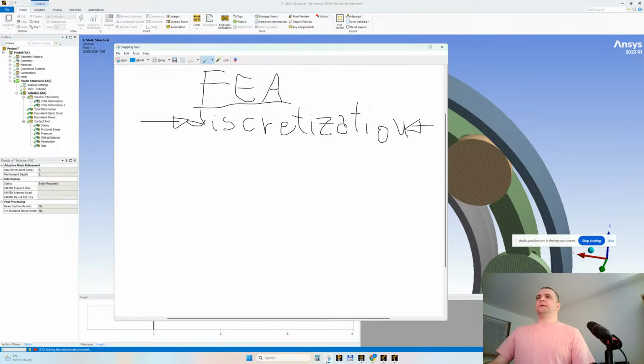Where were we? Here. Yeah. All right. We'll talk about FEA discretization. What I mean is, if we have the patience to discretize everything, in principle, we should be golden. We should solve anything and everything, in principle, if the model is somehow correct. I'm talking about the geometry and the materials and the loading conditions. If they are correct, applying discretization at all levels, it should work. Let me tell you what discretization means.